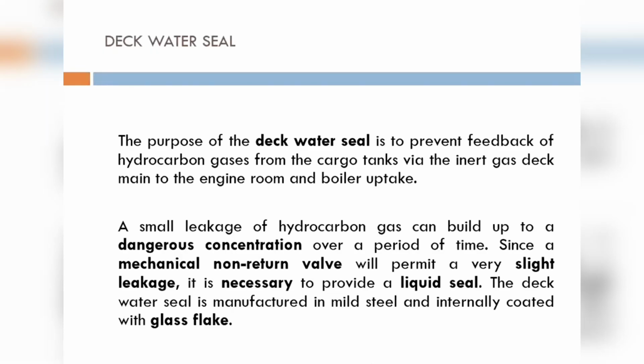But with time, with age, due to the acidic nature of the inert gas, this mechanical NRV will allow a small concentration perhaps to pass through, whereas the deck seal works by forming a water seal. With age, it will not affect the water seal, nothing will happen to it. So it's a 100% guarantee that hydrocarbons will never pass through this water seal. That is why the deck seal is much more reliable than the mechanical non-return valve, and it will never allow these cargo vapors to pass through and go towards the engine room. That is the purpose of the deck seal.